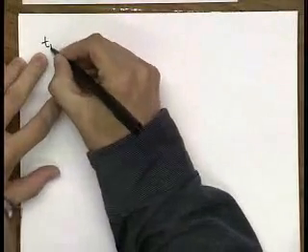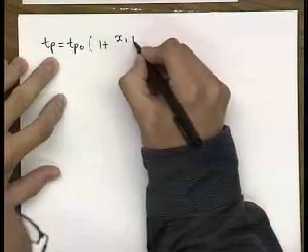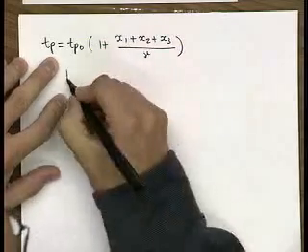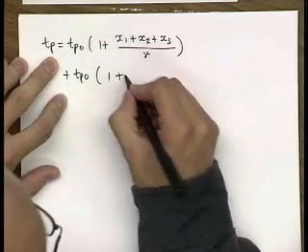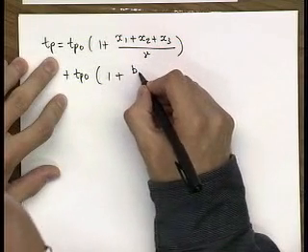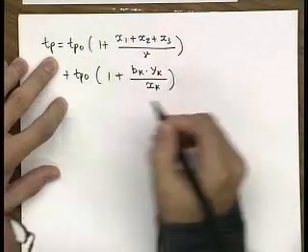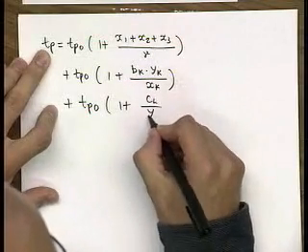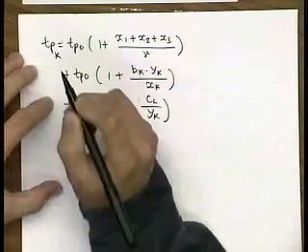So your delay is equal to Tp0 times (1 plus (x1 plus x2 plus x3) divided by gamma), plus Tp0 times (1 plus the branching delay b_k times y_k divided by x_k), and then finally you have the third stage, Tp0 times (1 plus CL divided by y_k). Now, this is the propagation delay tp_k for each of the branches.